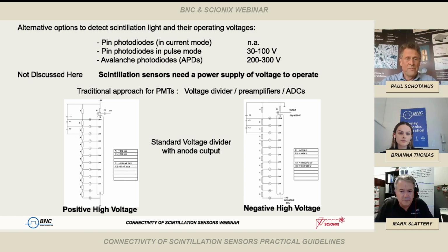You can do both. The big difference is that electrons don't want to swim upstream, so the cathode is always lower than the anode. When you have positive high voltage, a separation capacitor is needed to extract the signal at the anode, like you see there to the left. With negative high voltage, the coupling out is on DC, which has an advantage for some applications.